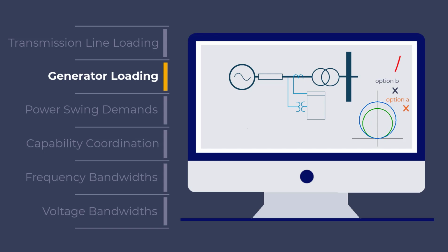Realistic overload scenarios are derived from power flow calculations, based on the generator's real and reactive power, voltage levels at step-up transformers, and the plant's internal impedances.